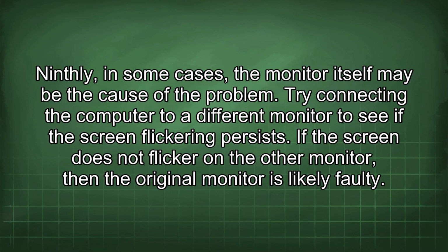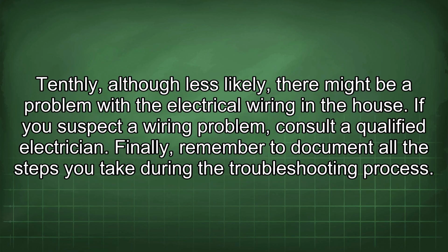Ninthly, in some cases, the monitor itself may be the cause of the problem. Try connecting the computer to a different monitor to see if the screen flickering persists. If the screen does not flicker on the other monitor, then the original monitor is likely faulty. Tenthly, although less likely, there might be a problem with the electrical wiring in a house. If you suspect a wiring problem, consult a qualified electrician.